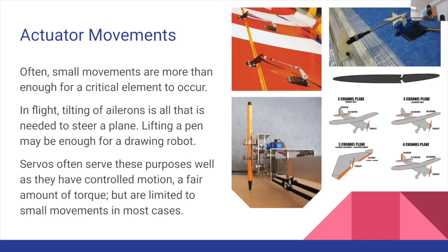And servos are a really good way to make actuators. They've been used in hobby RC planes for a long time because they're very lightweight. They behave very predictably. And basically the standard communication protocol for a servo is set by RC hobbyists. They've been using them for so long that they have set the electronic standard for how a servo works, which is really fun. Servos can do this job really well. The very small light ones are pretty wimpy, but you can get very, very beefy servos. So it's possible to really upgrade all of this.